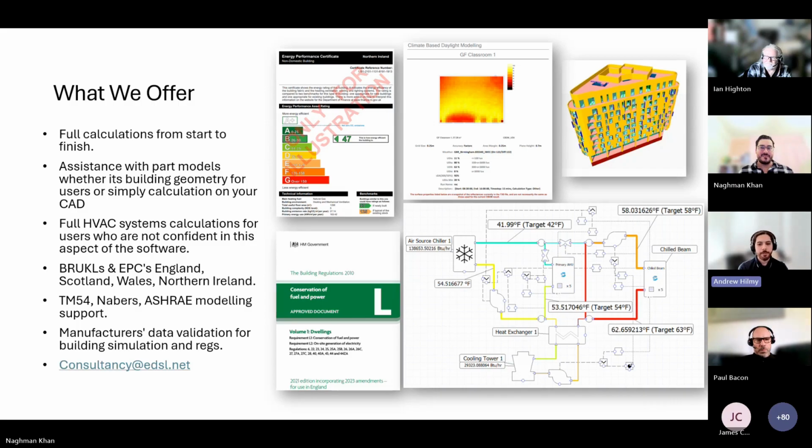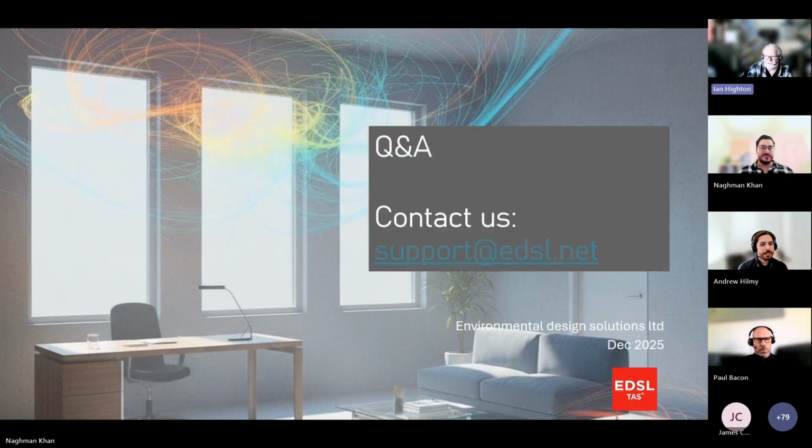So that's quite handy. And I mean, the other thing as well, in terms of future development, we're hoping to integrate Systems with Ambience 3D, which is quite exciting. But that'll probably be a future webinar. Yeah, so that's basically taking the HVAC supplies, extracts, positioning them within the CFD calculation, and then doing that in exactly the same way we do the NAT vent at the moment.